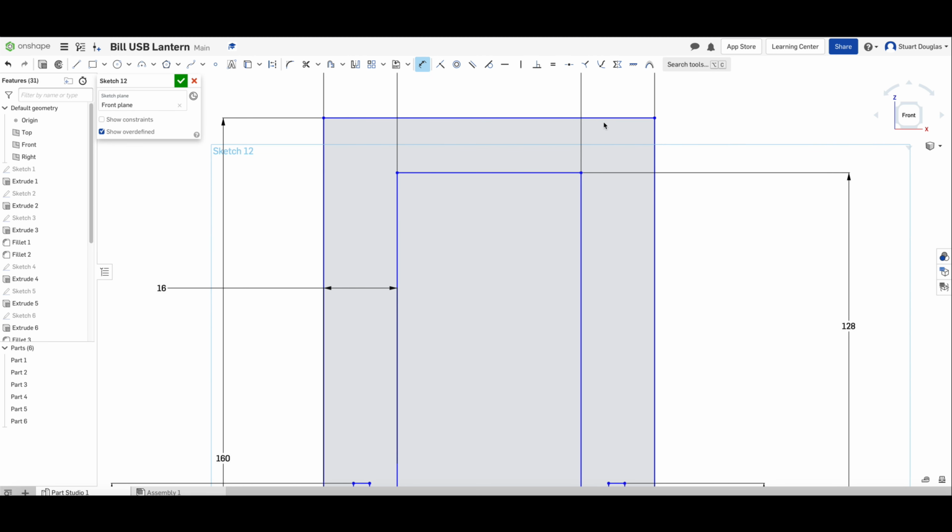Okay, in order to do that, we're going to use the rectangle tool, and let's add 2 rectangles at the top of our work. This rectangle, we know, based on our other rectangles, the dimensions in terms of the width. Let me undo. Dimensions in terms of our width are 3.5. So let's change that to be 3.5 and do the same for this one. These 2 rectangles are 21.25 millimeters from the edge.